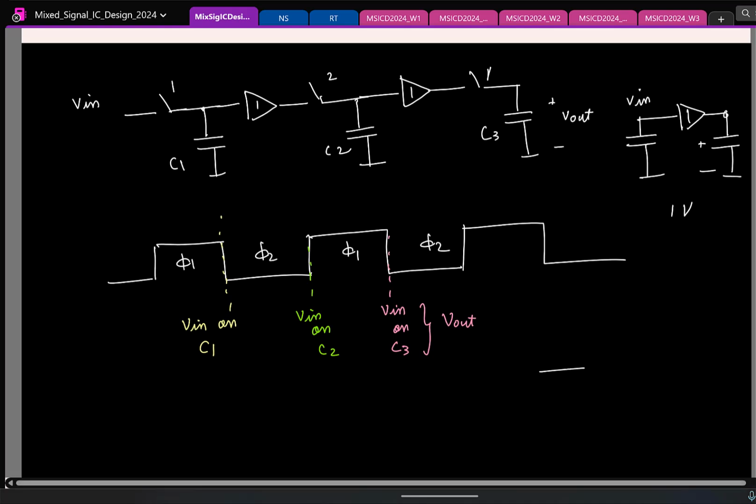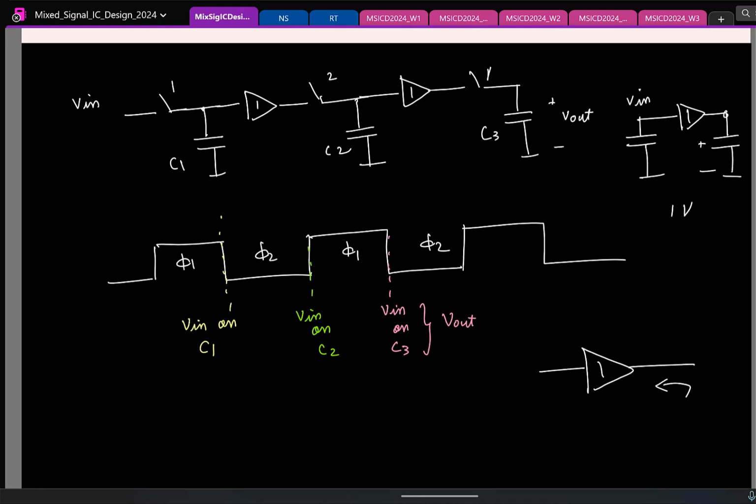Because ideally, what is the output resistance of a buffer? Output resistance is 0. A buffer is a voltage controlled what source? Voltage source. So the output resistance of a voltage source is 0. From the output side, you have R and a very small resistance. So it instantly discharges. Any initial voltage you have will instantly discharge, and whatever current you have will only get added. Okay.